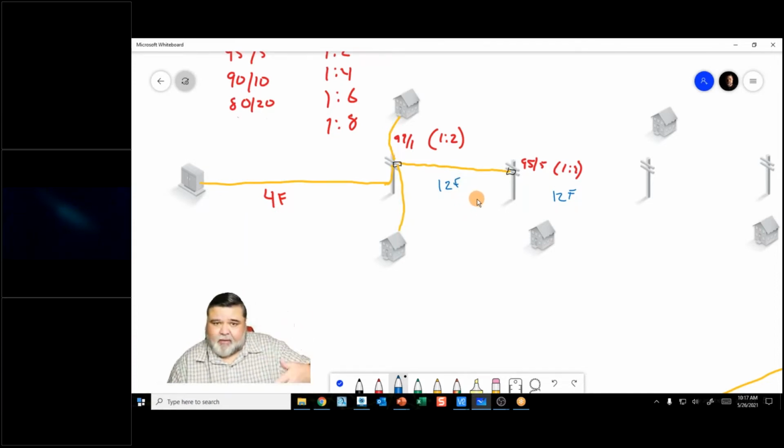If you put a big cable up there and try to do an overlash, I don't know how many times, back when I was doing line work, you'd have to get up there and upgrade your strand. And then all the down guys and resag all the poles and all this stuff involved, right? You'd have less complications on the construction side, on the splicing side, and on the testing side. And that's what's happening here, right? Is we're splitting the signal. And this is all just one fiber, right? It's all just one fiber.